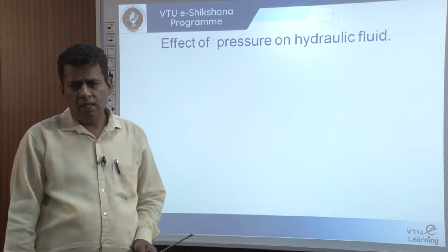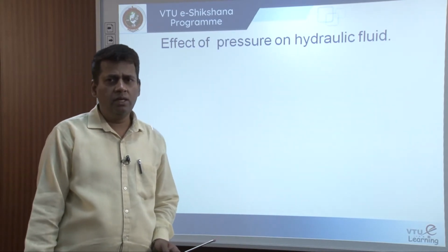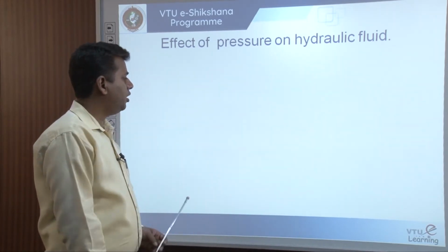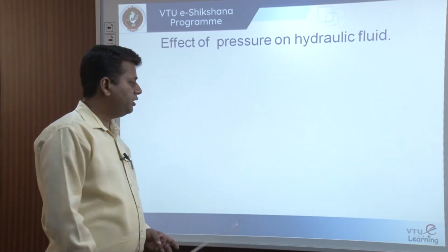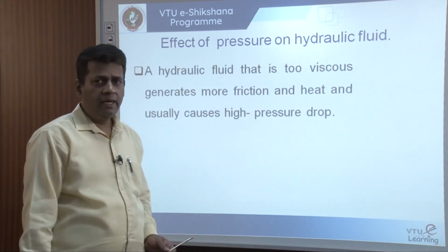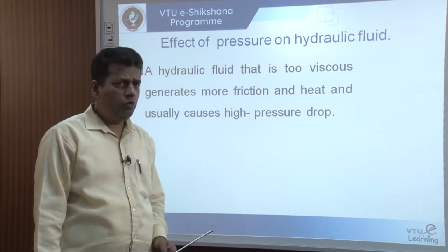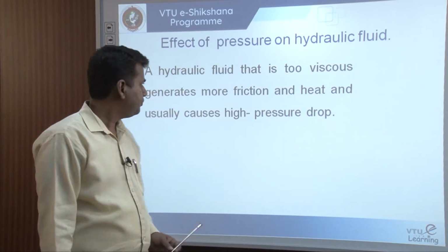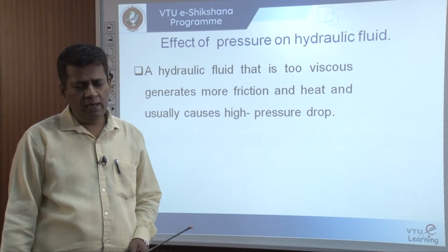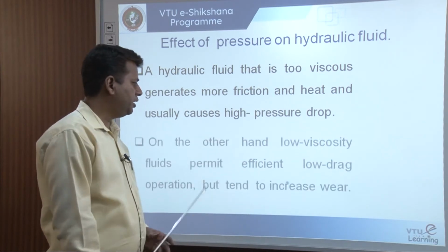Next important effect is the pressure effect. The previous was the temperature effect, now it is the pressure effect. Now, we need to know the effect of pressure on hydraulic fluid. We know that temperature and pressure are interdependent. So, a hydraulic fluid which is too viscous generates more friction compared to the oil which is moderately or less viscous, because of high pressure drop.